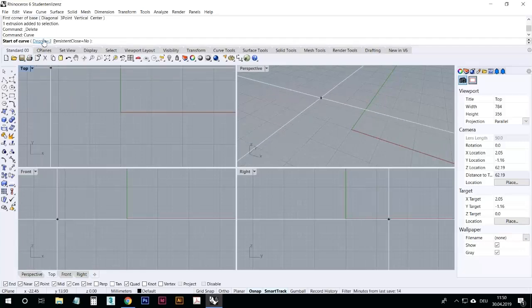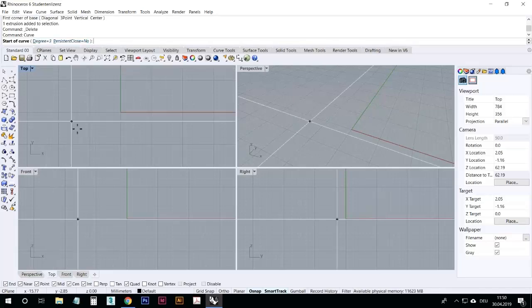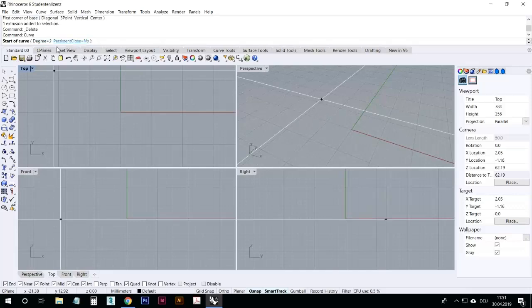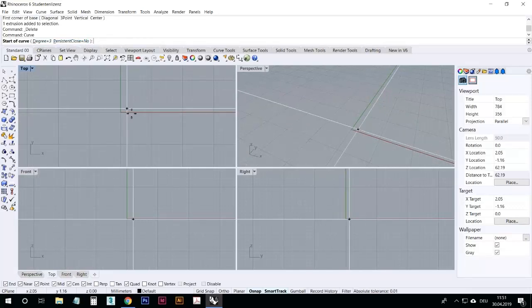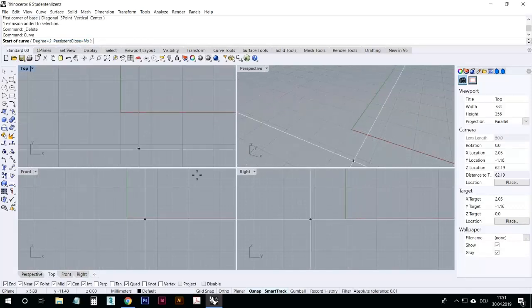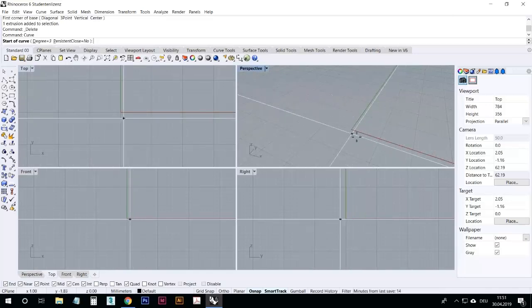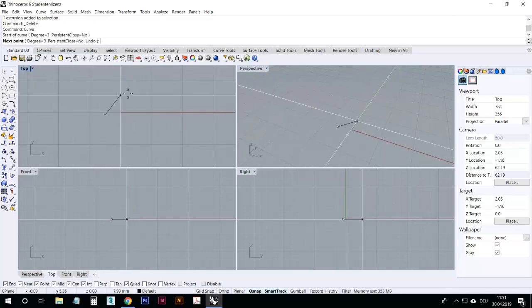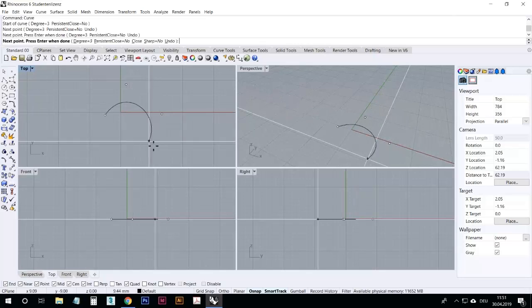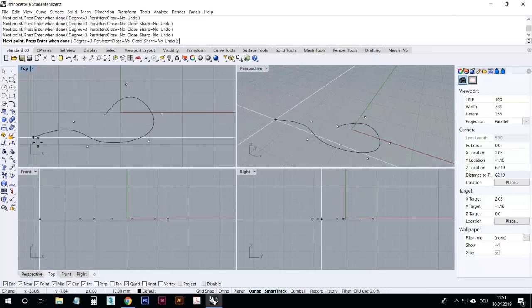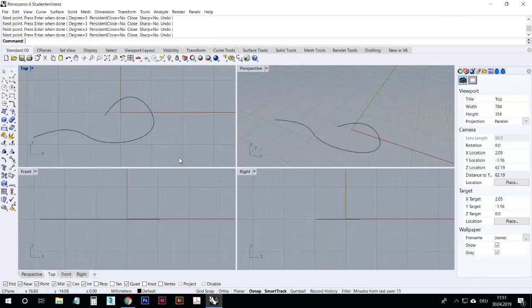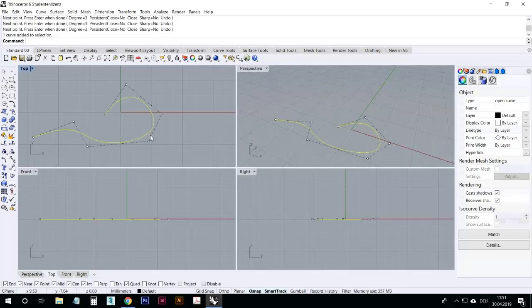And we have also additional questions, and you see here, if you click them, you can actually change the degree of the curve. I will talk about the degree later on, but you can now already answer the question by clicking in some of these windows. For example, like this. You continue clicking until you are happy with the result, more or less, and then you click either enter on the keyboard or right click on mouse. So that's more or less how you do it.